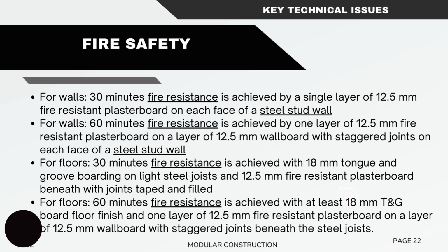For floors, we have 60-minute fire resistance achieved with at least 18 mm T&G board floor finish and one layer of 12.5 mm fire resistant plasterboard and a layer of 12.5 mm wallboard with staggered joints beneath the steel joists.